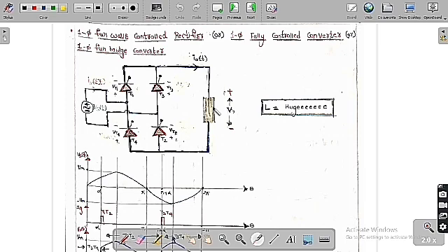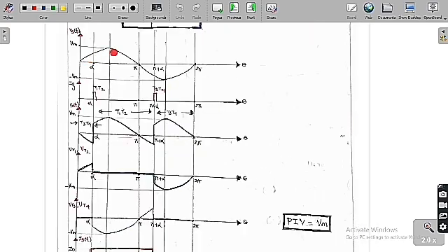So therefore the current I naught of t is always a constant value. So based on this, now we are going to analyze each and every aspect of the graph. This is the source voltage, which is Vs of t equal to Vm sin omega t. This is the graph we are going to get. From 0 to pi it is positive and pi to 2 pi it is negative, with the peak values of Vm and minus Vm.